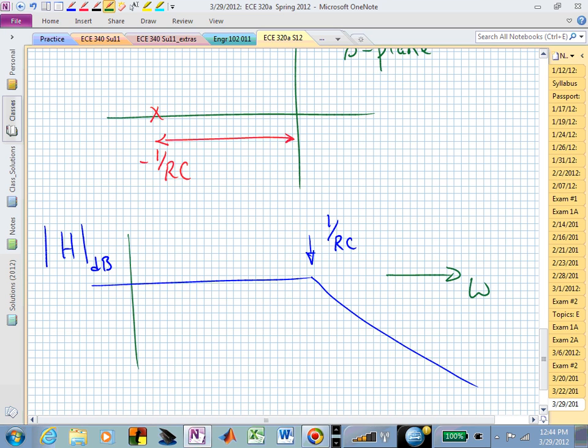And what's the order of that low-pass filter? First. And that actually influences the slope of that line. This will now be going down at 20 dB per decade. And what's a decade? I'm giving you some background to advance your thought process, so when we do jump into Bode plots, you're going to be ready to be at least jogging and not crawling, is the idea. What's a decade?